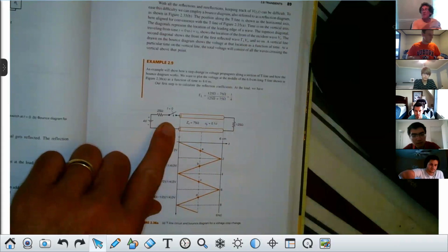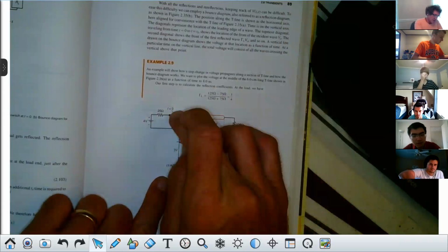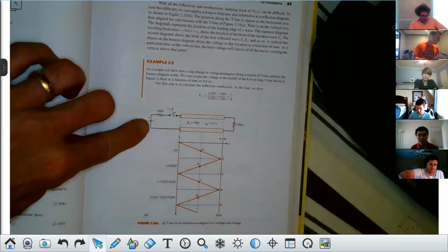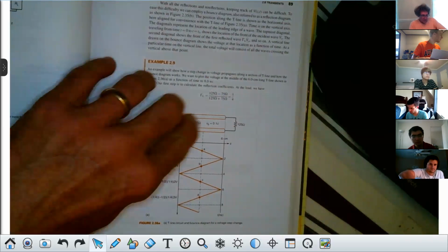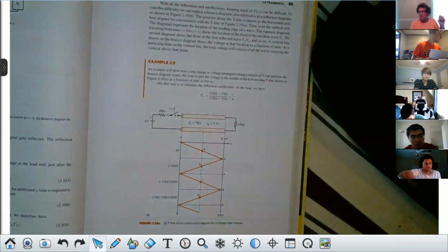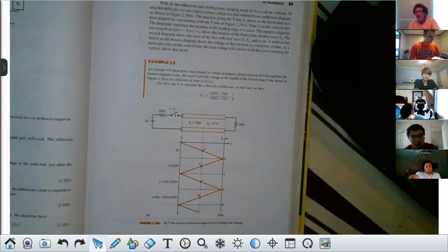As time goes to infinity, they look just like good conductors. So it's like that 125 ohms is just stuck right there at the beginning, and the transmission line doesn't exist. So the voltage, as time goes to infinity, will just be found through voltage division. You would take 4 times 125 over 150, the source resistance plus the load. That's what it is as time goes to infinity.